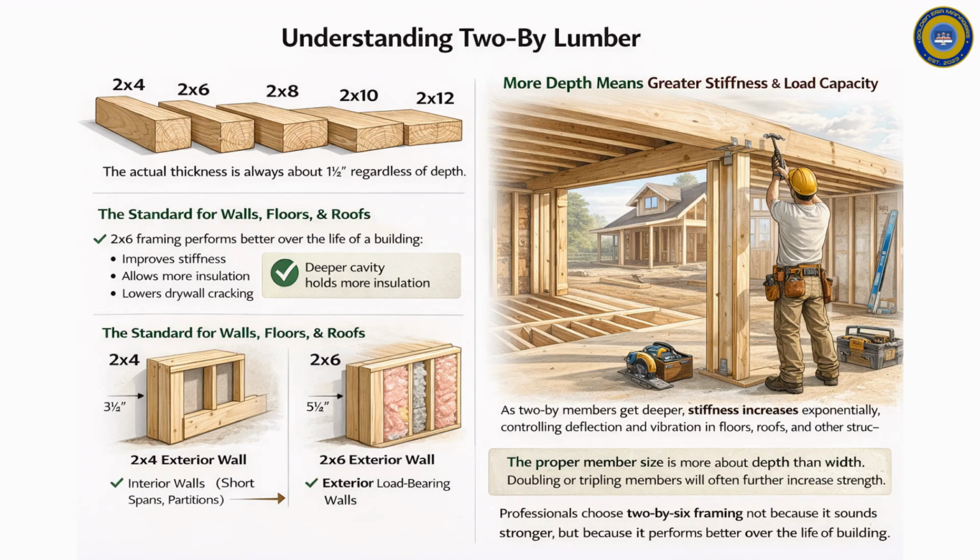When floors feel bouncy or roofs feel flexible, the issue is almost always insufficient depth, not insufficient strength. Understanding this principle explains most professional sizing decisions. The goal is not to meet minimum code. The goal is to control deflection, vibration, and long-term movement so the building feels solid years after it's occupied.